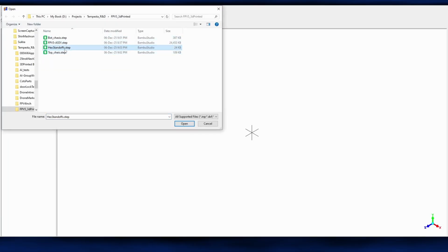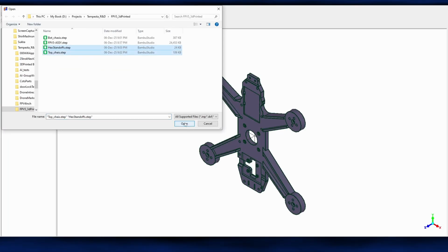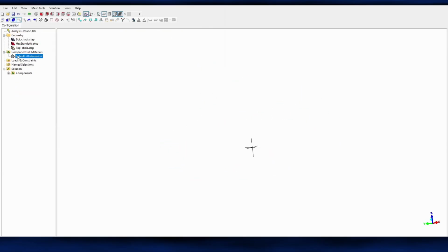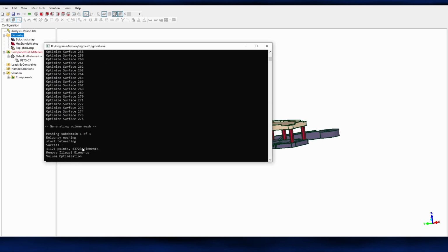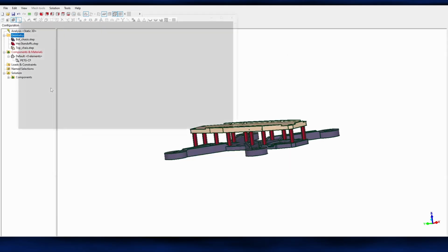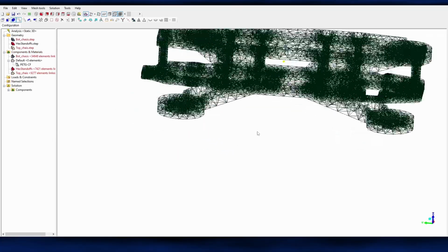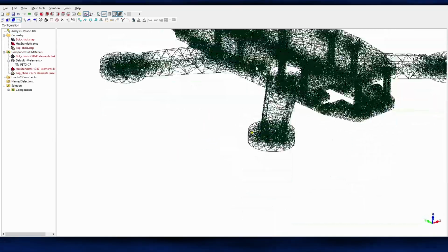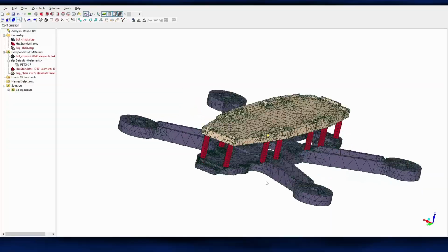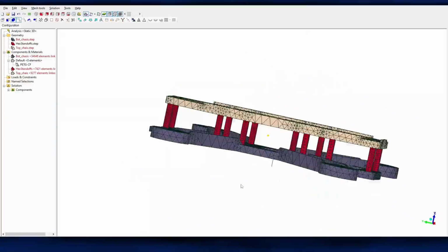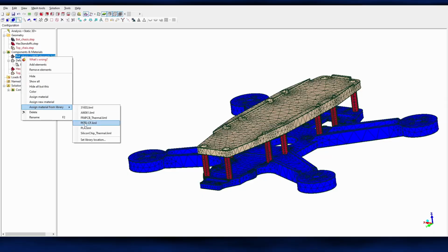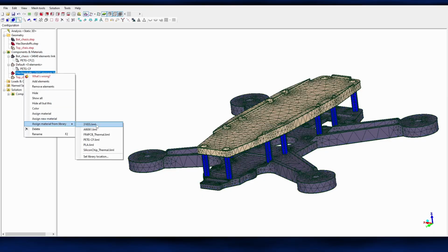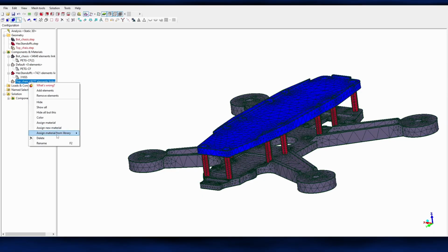Okay, finally. Open new project in Mechway. Import all the assembly STL files. Next, mesh it and review that all looks good and no missing elements. Define the analysis to be 3D static. This drone is constructed out of a few materials, like PETG carbon fiber, PLA, and the standoffs are made of 316 stainless steel. So it is important to set all properties correctly.